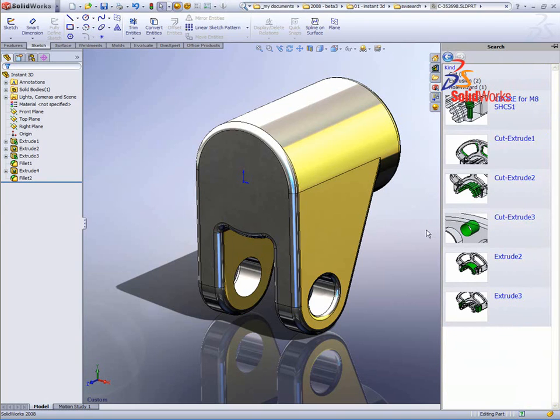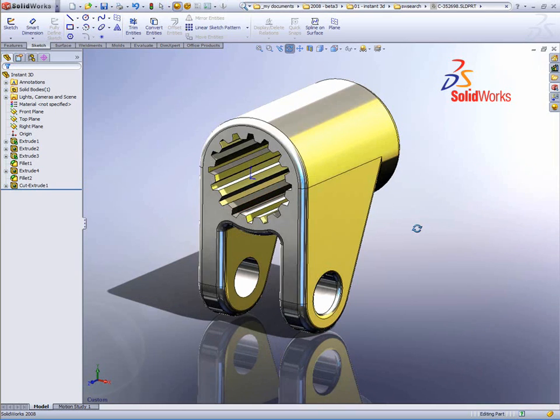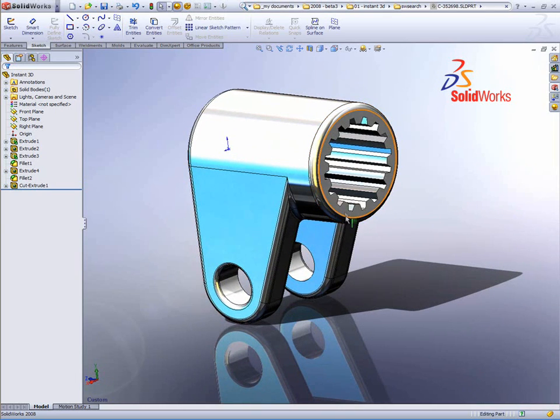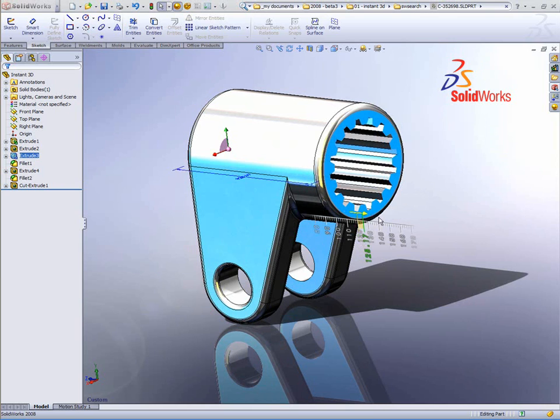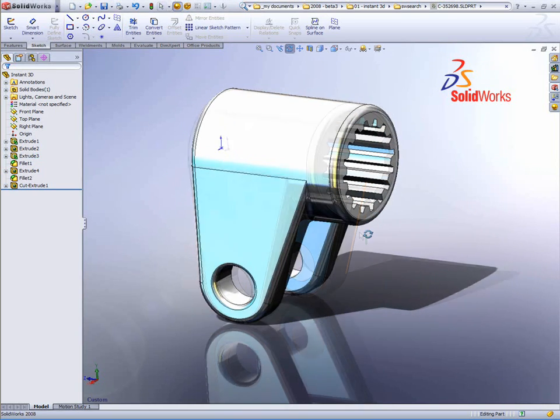Again, it takes me into the dissected information for this feature. Before we reused a sketch. This time I'm just going to reuse this feature and drag it and drop it onto that face there. You can see it creates a through wall cut so that no matter how I move this end of my part out, it's going to always remember that that's through wall.